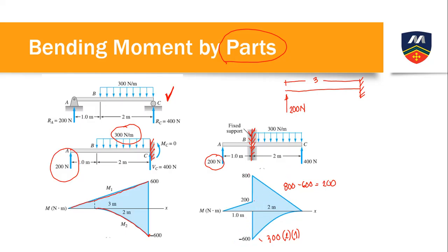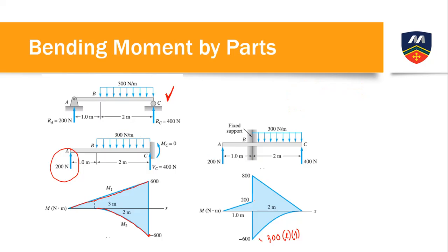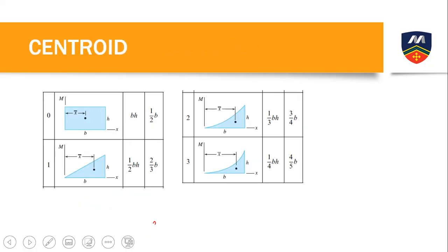a moment diagram. We set up the cantilever first, then make a moment diagram for each load. You make a moment diagram for each load one by one. Okay? This is what we use to get the moment area of the moment diagram, to get the slope and at the same time the deviation. However, for the computation of the deviation, for example, B relative to A, that is just the area.